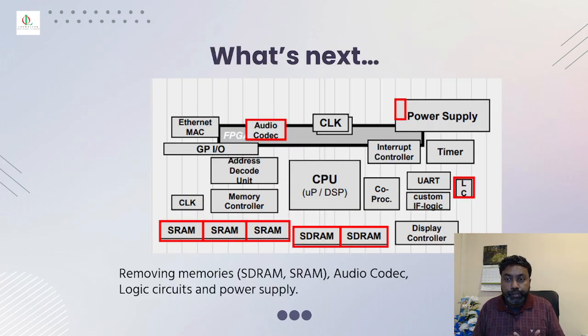So how we can reduce: the power supply unit that's used in the traditional photo that you saw dissipates plenty of heat, so it reduces the performance of neighboring devices. So that can be removed and connected from outside. And the traditional embedded system used an audio codec. FPGA is purely digital, so the audio codec can be interfaced from outside the FPGA.